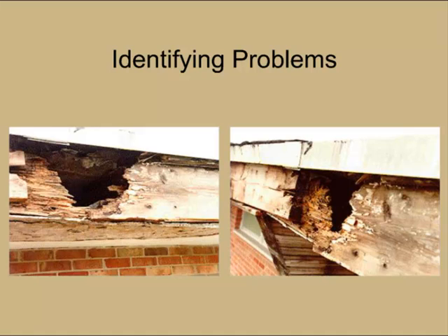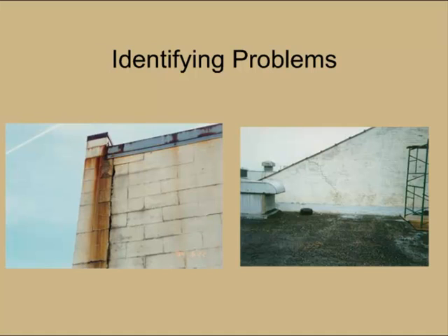Moisture is a very aggressive material. These concrete sections here, in this case, the reinforcing steel was placed too close to the surface, so when the moisture absorbed into it a little ways, it was able to start a corrosion effect there, which broke the surface concrete off, and it will continue to get worse the longer it's exposed.